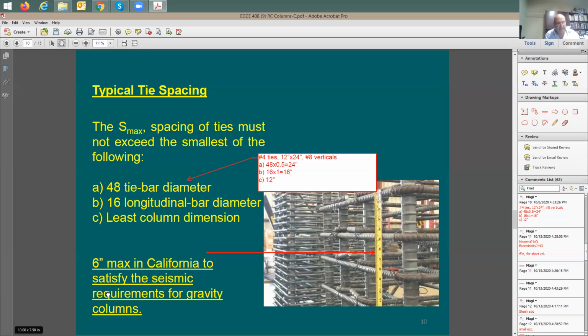Are you guys okay with this answer? Does it make sense? I'm kind of thinking of an oscillation, like if the ground is moving, it takes a little longer for the lateral movement to reach the top, correct? Well, the movement is going to happen for the building for all members, all columns, seismic and non-seismic, gravity and seismic members. This is the reason we also need to consider some seismic requirements on non-seismic columns: you move them, you strain them, you drift them. It is true that they are not designed to support these lateral forces, but they're exposed to lateral drift. Roger that. Okay, very good.